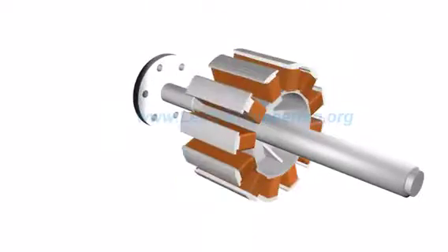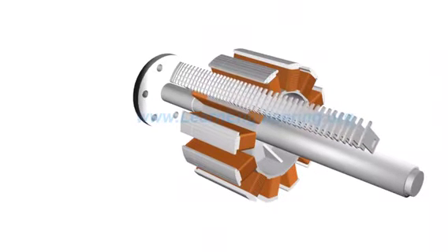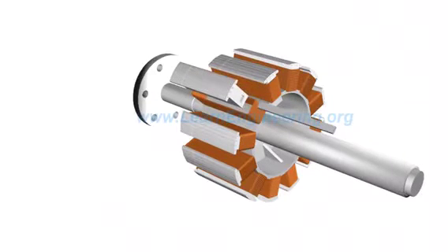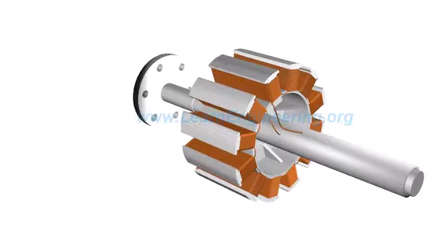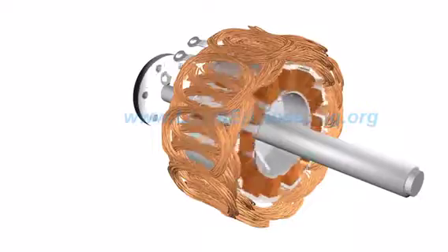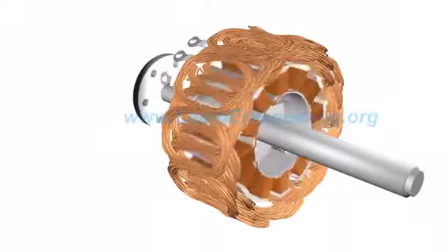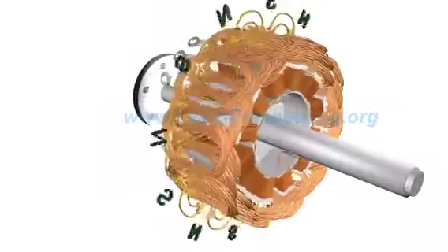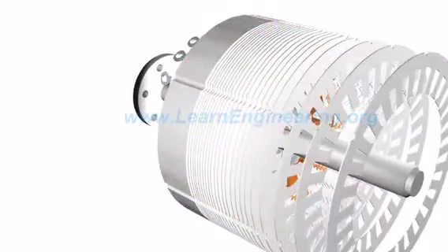The pole core is used to effectively transfer magnetic flux, and is made with fairly thick steel lamina. Such insulated lamina reduces energy loss due to eddy current formation. Armature winding of a 3-phase, 12-pole system is shown here. A stator core is used to enhance magnetic flux transfer.